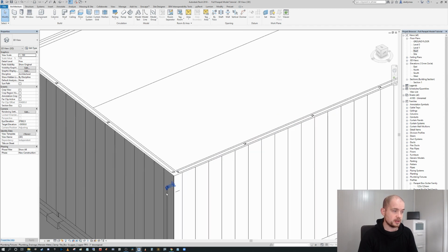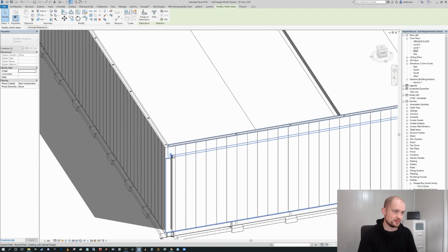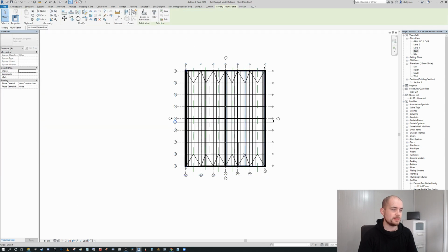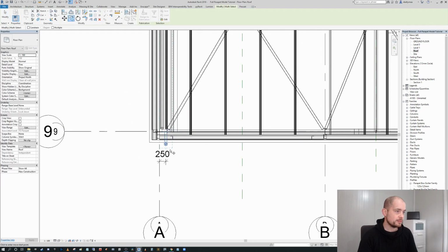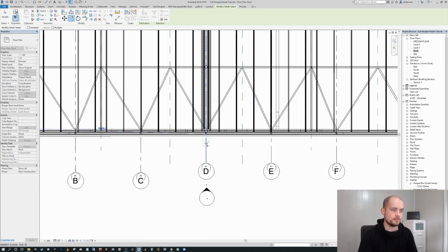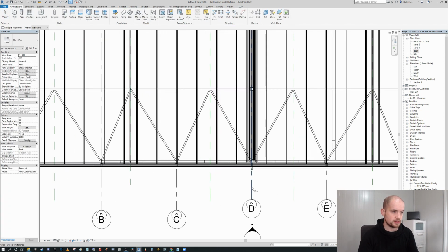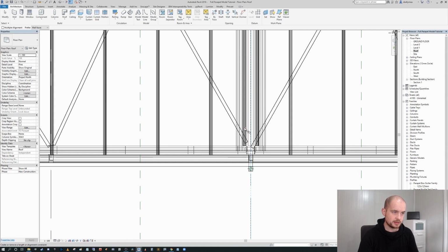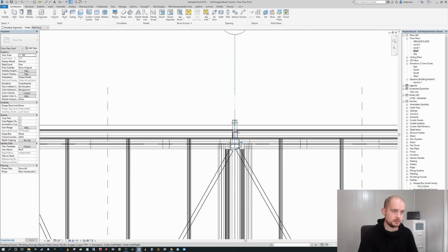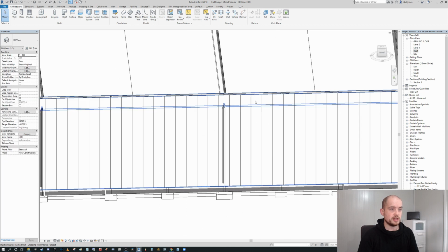And again, we probably need scuppers obviously on our internal now that I think about it. That would help, wouldn't it? So I'm just going to go down through here and selecting the elements that we have. I'm going to bring them all the way across and attach them to our mid-grid here. Okay, and again, I'm going to align the scupper to that grid, and I'm going to lock. Okay, so our roof drainage now is complete.